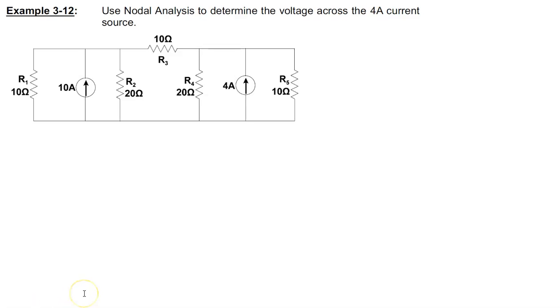And so for nodal analysis, we have a step-by-step process to go through, and one is to analyze the circuit to determine the number of nodes. The reality of it is that we don't really want to call this a node and this a node and this a node, because these points are all connected together. So they are points of equal potential. And so I suppose we want to call that a junction. All it is here is at the same potential. And so that's a node.